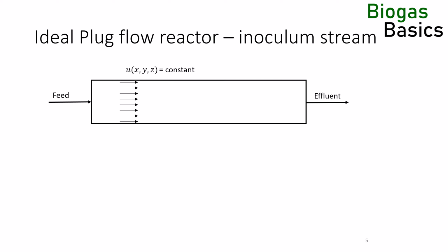Even if the feedstock is pH neutral and contains all required microorganisms of the AD process, the microorganisms would still need to grow while the fluid element travels through the reactor. At the inlet of the reactor, where the substrate concentration is the highest, and the reaction rate should be the highest as well, the microbial biomass concentration would be the lowest. In the first part of the plug flow reactor, very little would happen. The maximal biomass concentration would be at the end of the reactor.